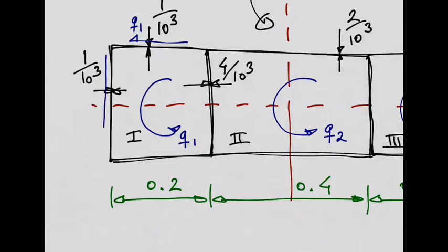Then in this wall here, flowing as well. Q1 is the same Q1. Don't you remember last week I told you the shear flow in torsion is constant in the cell, right? It will flow then in this wall as well, Q1, and then it will go up in this wall, also Q1, okay?